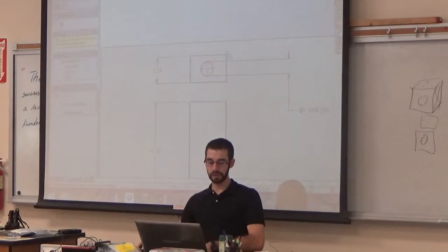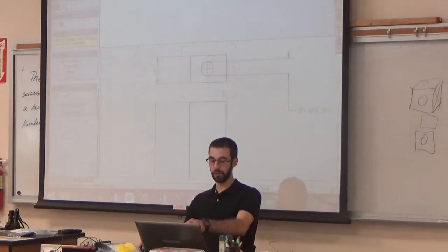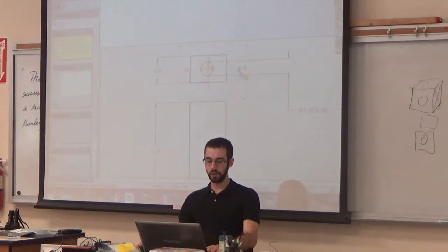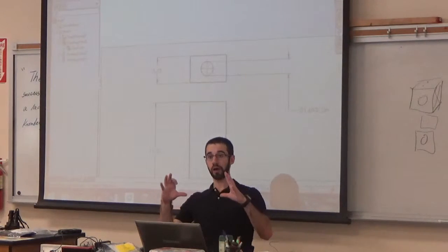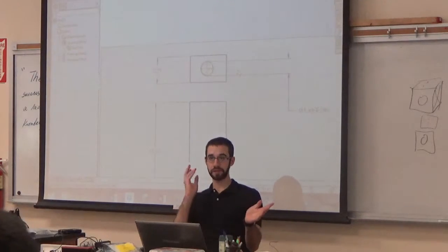A better way of doing that is actually to draw center lines. Actually it's not on the center, so it's a good thing. The better way of doing it is to draw center lines from top to bottom and across, which match up with the circle. That's poorly done, but basically you want the center lines of the box to match up with the center lines of the circle. That way you can say it's in the middle.